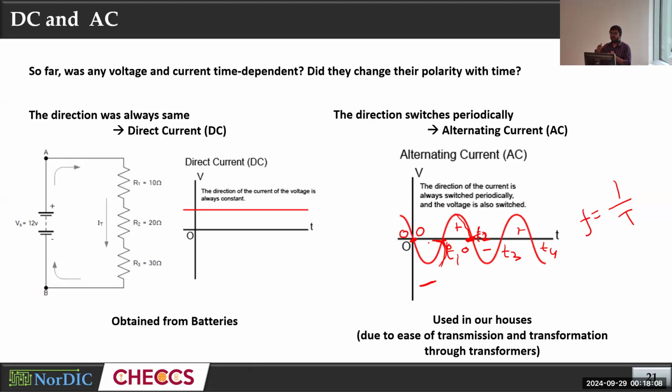Is it clear? So we can actually increase the AC, and before our home there is a transformer. The transformer is responsible for increasing and decreasing the voltage, step up and step down. With the transformer, we first step up, we distribute that through wires, and we go to the transformer near the home. We then step down, whatever we may be getting, like 500, 600 volts, to 200, 220 volts, which is suitable for electric products. Then we use that in our home.